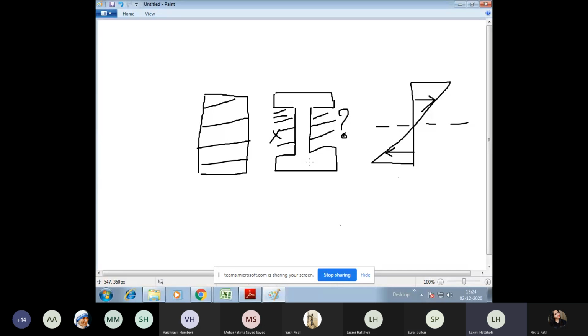See, for both the cases, you are getting almost the same pattern of bending stress. So which is economical? That's what I'm speaking about now. Can you tell me which is economical? I section. The I section is economical. Are you getting my point? For the same cross section, you are getting the same stresses. Then why go for the rectangular section? You provide the I section. That's the meaning, and that's how you need to give the justification for the economical section. Is that clear to you?